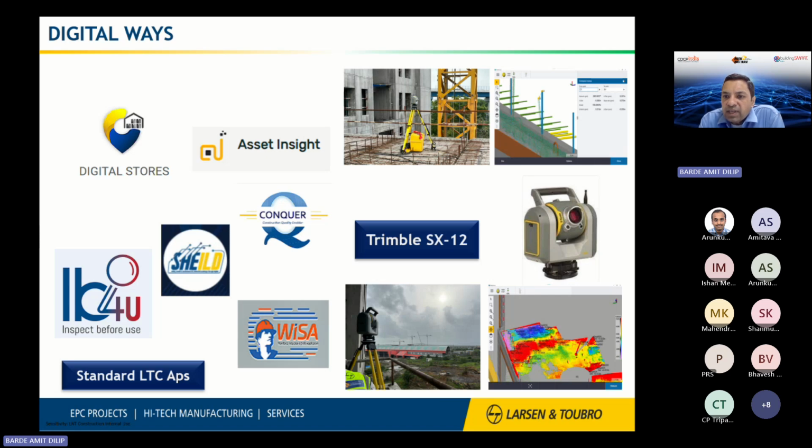And here in one scan, we are able to see what my BIM model is and what my actual dowel is and how much is the deviation, or if I need to do anything, which earlier we used to do at each dowel, we had to go and survey and measure and then do. This is happening at a much faster level.